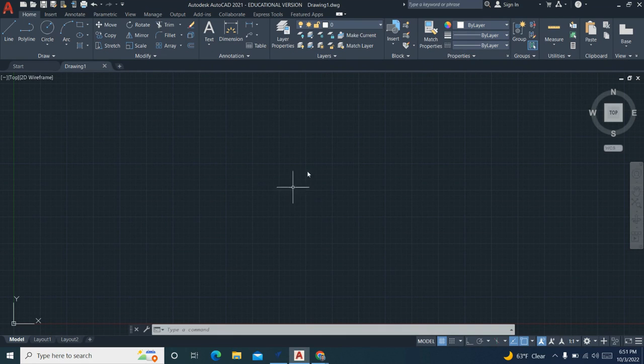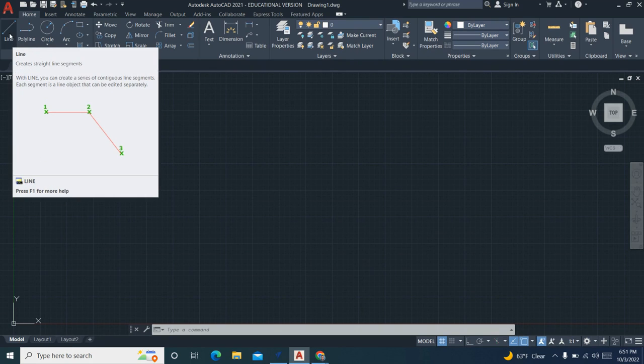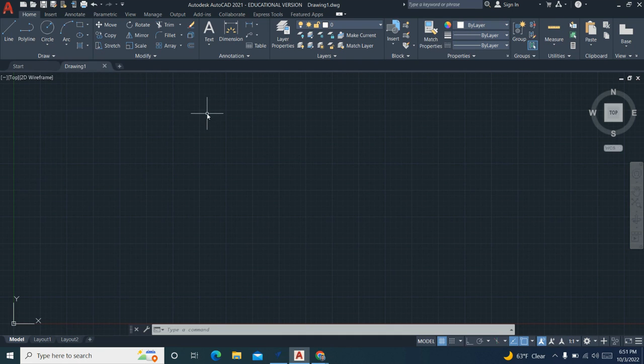So what I'm going to be teaching you today is how do we take an AutoCAD DXF file and transfer that into V-Carve Pro. Now, you're probably watching this video because you've already tried to do this yourself, or maybe you just don't know. Sadly, transferring a DXF from AutoCAD to V-Carve is not as simple as saving it or exporting it. So we're going to go through the nuances and the few extra steps we have to take to make sure that this is an actually transferable file.